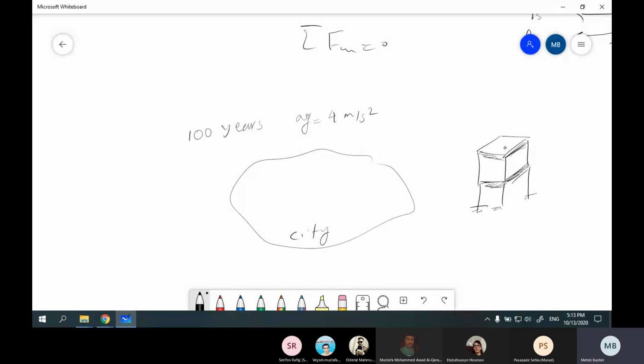If I tell you this dimension is 5 meters and this one is 3 meters, and you are using concrete, what is M? With a thickness of, for example, 5 centimeters. If you have the weight of this part, as I said, roofs and floors are the massive parts. So what is weight? Gamma times volume.